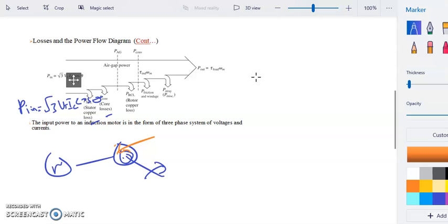Meaning the copper or the aluminium cage losses. And then after conversion into the shaft, the losses happen in the friction and windage, and the miscellaneous, which is called the stray loss, a percent of the losses compared to the full load rating or full load power range. The friction loss here happens in the bearings, and the friction between your stator and rotor.